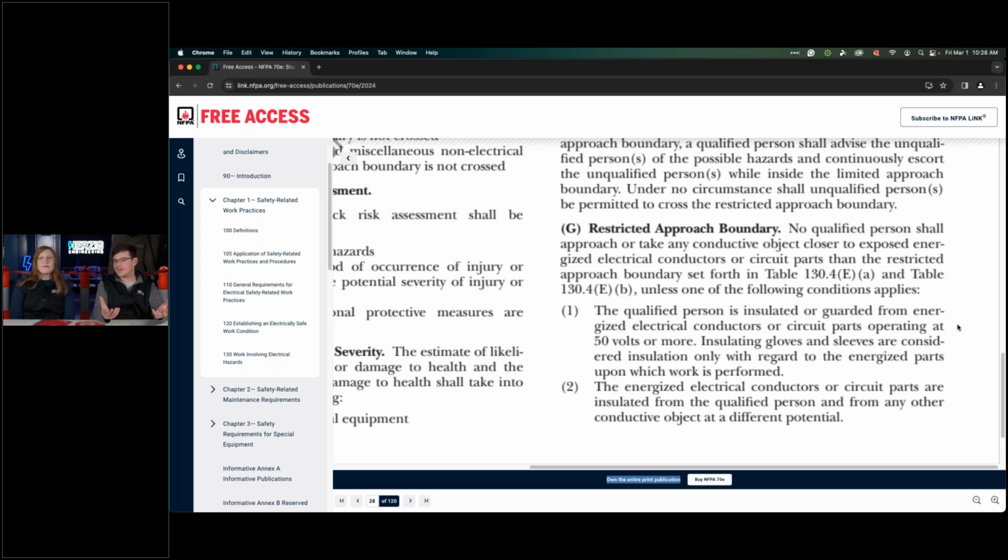Conductive items that are on your person that don't need to be on. You know, uninsulated tools, improper tools. Absolutely. So metal frame glasses. I could keep going. Exactly. Nothing that makes it easier for that electrical arc over, basically. Nothing that'll help the current leave its intended pathway.